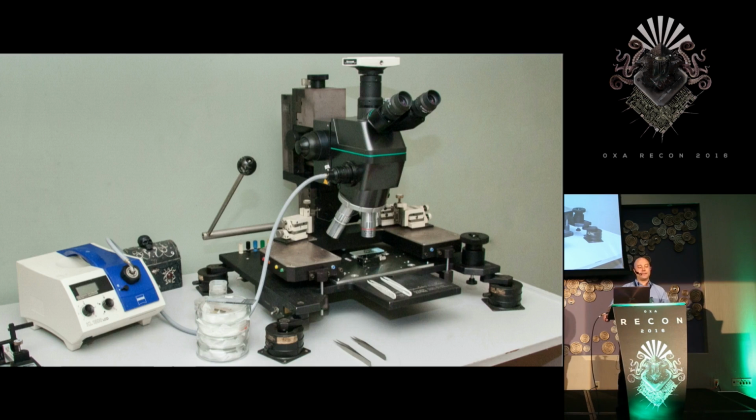So next I started an invasive study of the chip, studying it under a microscope. Now, microscope costs can range from hundreds of dollars to tens of thousands of dollars, or even higher for electron microscopes and this kind of thing. I used a Mitutoyo FS70 microscope for the photos you'll see here. The FS70 is used typically for microprobing, but you can use it for other things also. I used it because I had it available to me. Really, for studying this level of technology, you could use a lot more basic equipment. But if you have something higher end, it's always nicer to use the higher end stuff.